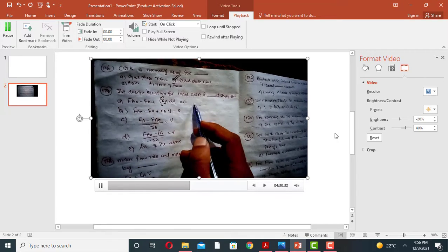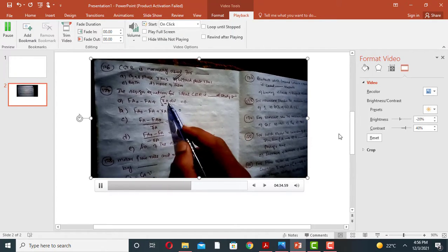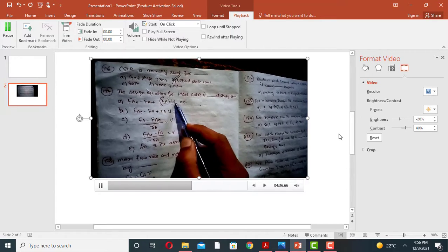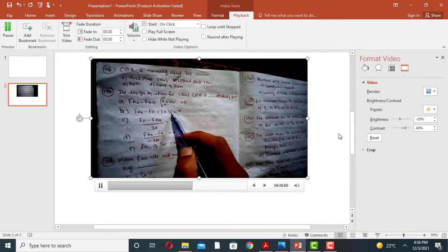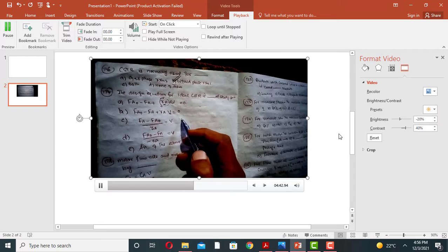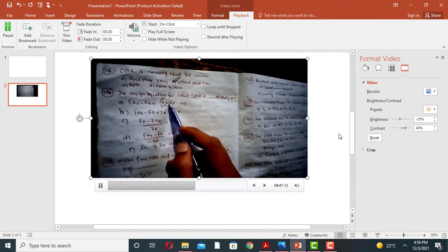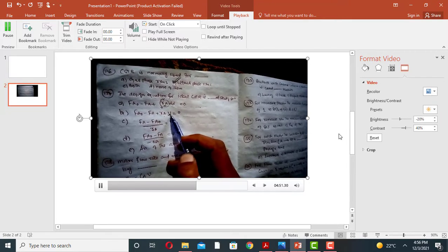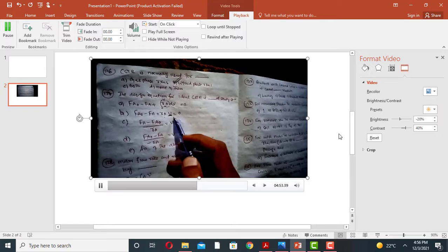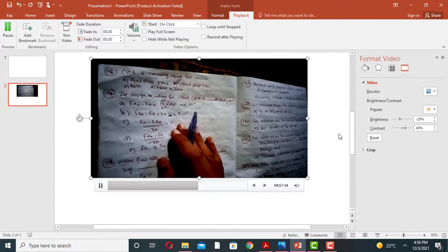FA0 comes to this side, and the rate is also constant, so integrating dV gives V. So this is FA0 minus FA plus rA times V equals 0.